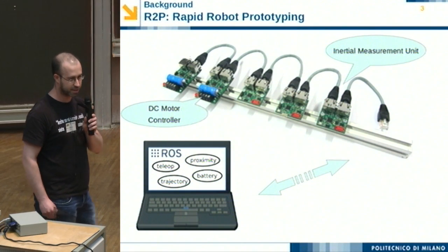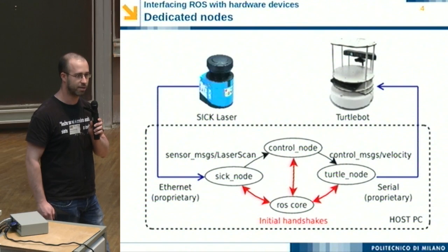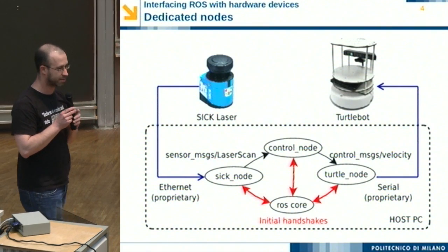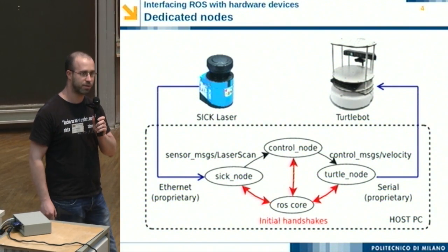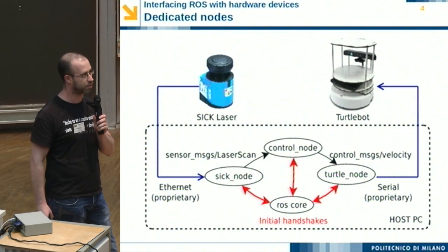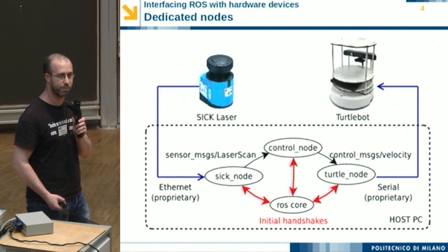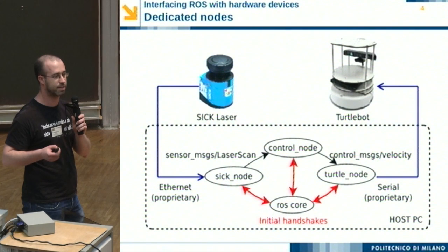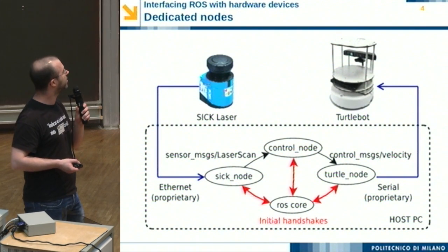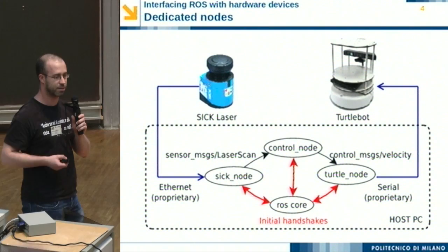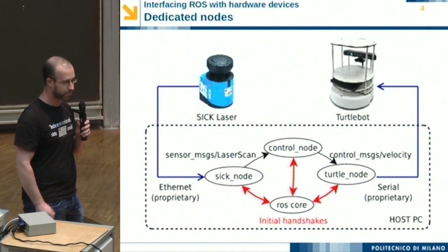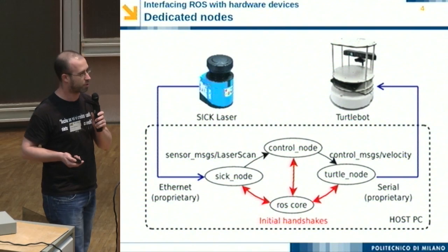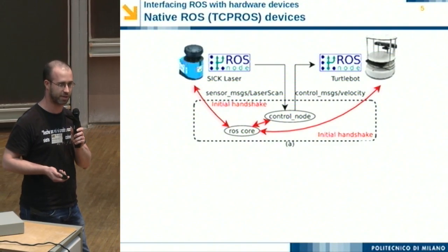We are happy ROS users, but the problem we always feel with ROS is when you have to interface with the hardware. Many devices use custom protocols on a serial connection or USB connection or even Ethernet connection, but still with custom protocols. So usually you have a software node for each device that is directly connected to the device, and then the software node publishes ROS messages over the ROS network. This is not, I feel, what the distributed architecture of ROS is fostering.